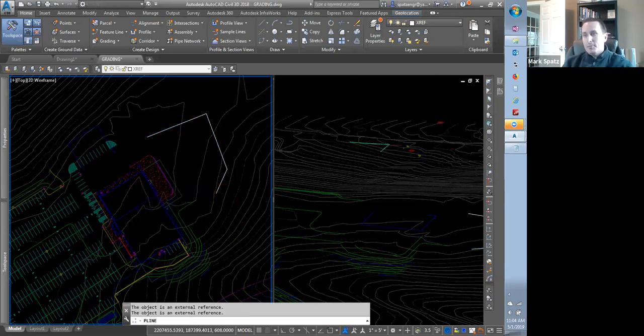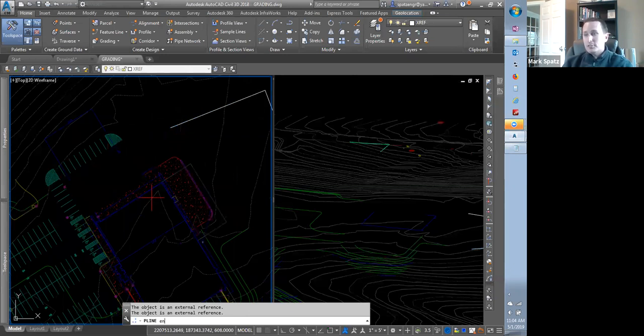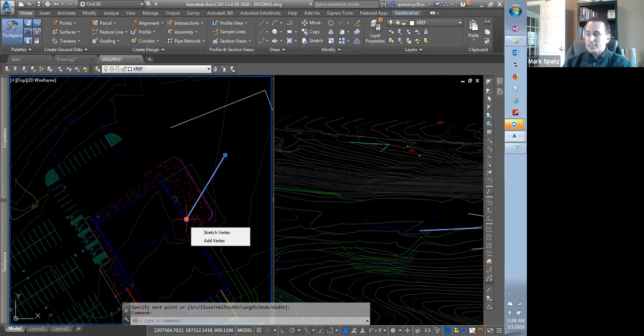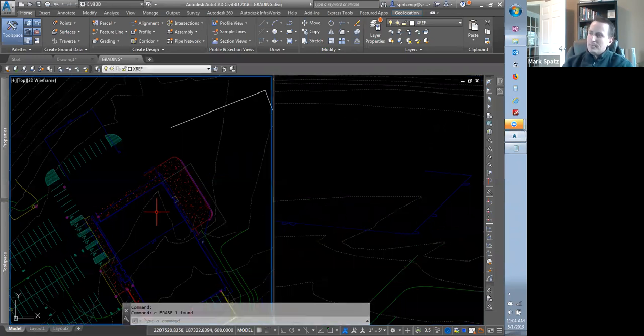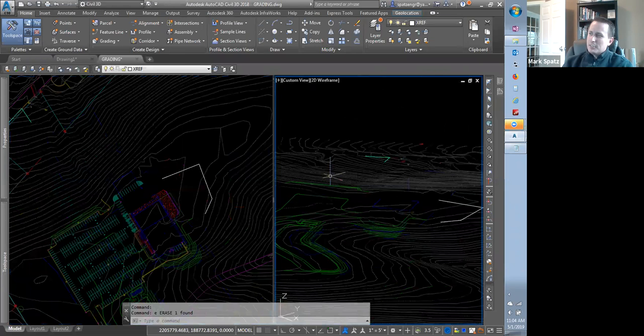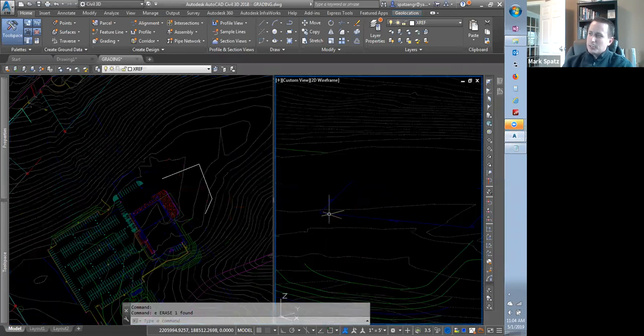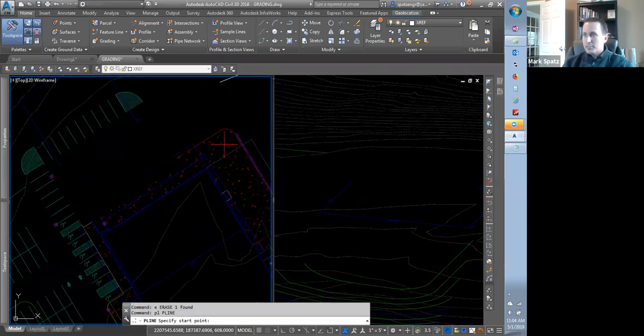Now, but if I draw a polyline and my OSNAP Z is turned off, so I'm going to grab and snap to this building corner and click over here, you can see that that polyline is not necessarily at 608. See that? It's at 609 because I actually unluckily snapped to something that is at elevation. Normally, you might start to notice things like this line work really shouldn't be up at elevation. So you might start to notice things that you can fix up.